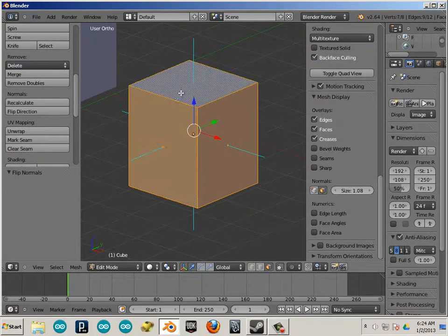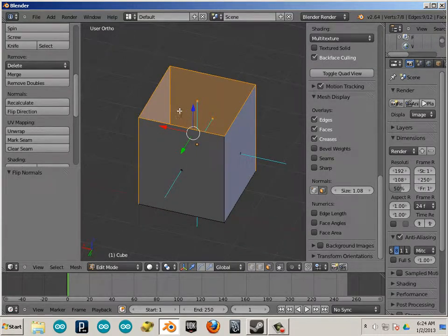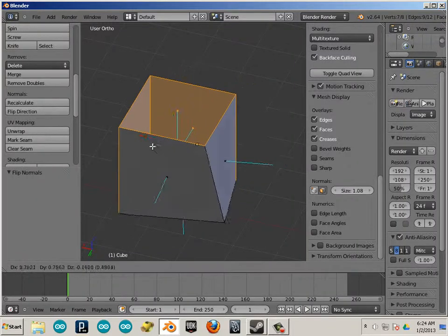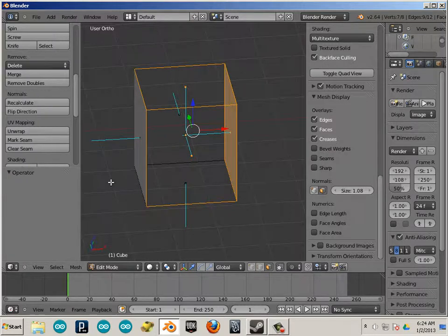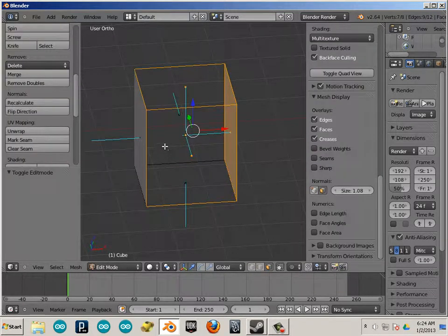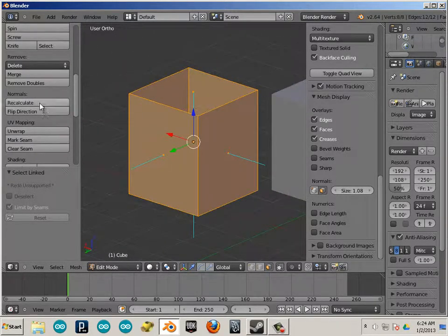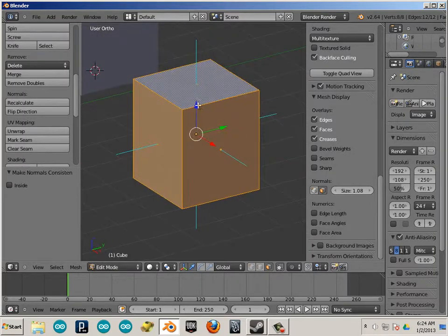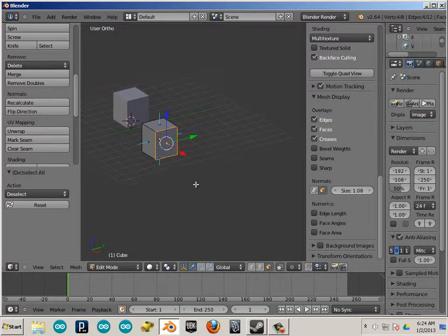But let's say I had two or three of these that were flipped inside and some outside. This is totally not legit. These will error out every time, anytime I have a mesh that has surfaces that are pointing in multiple different directions. You can fix this by sometimes hitting L on the keyboard to highlight all the components at once, and hit recalculate. In most cases it'll fix it, but let's say it's past redemption.